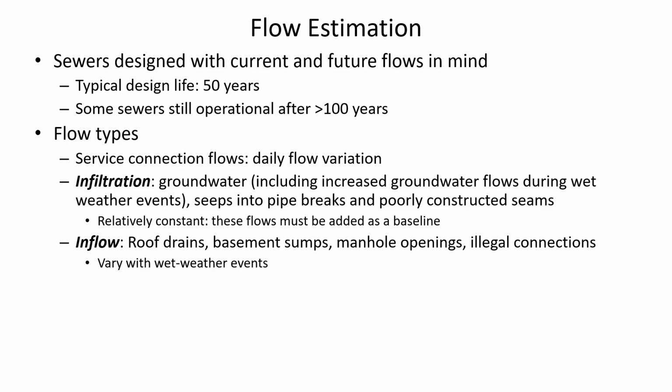But broken sewer pipes aren't always fixed in that same way, because we don't know if it's broken because there's no pressure signal. We can know if there's a crack in the pipe downstream of a drinking water pipe because suddenly people's pressure is worse than it was before.